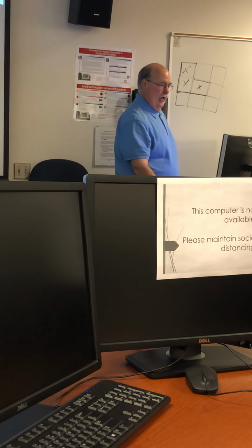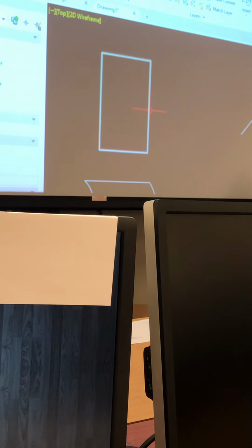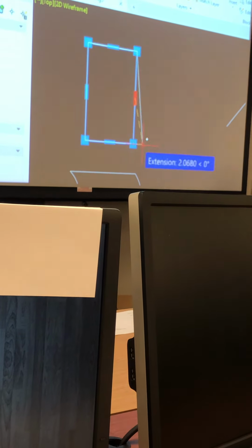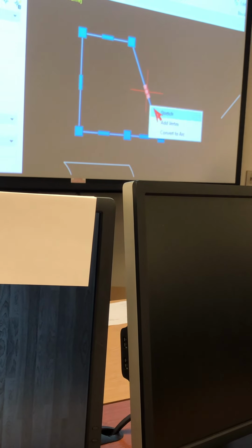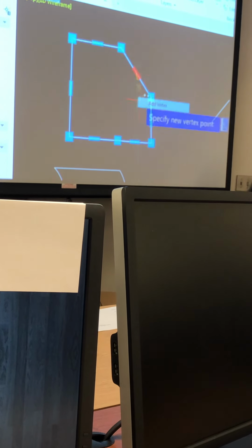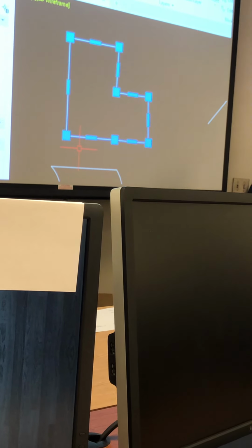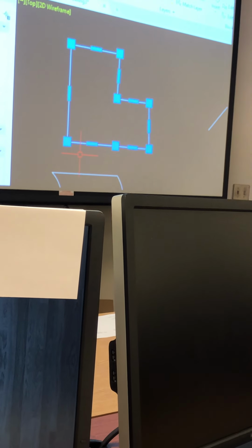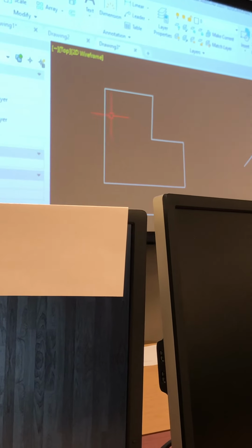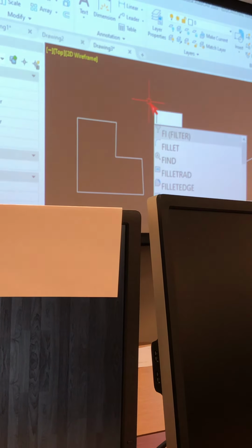So now we can go in and edit the polyline, and I'm just going to use a rectangle to demonstrate this. I can click on the rectangle and say add vertex, come over here and add a vertex, add another vertex, add vertex, and basically redraw the shape without having to explode it. And you're probably saying, what does that matter if I explode it? Well, some companies will actually use fields, which we will get into. It's called a field object.